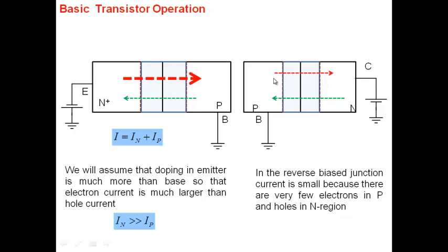It's easy. In fact, it's not difficult for an electron to go from P to the N region. If you look at the direction of the electric field, it helps the flow of electrons. So that's not the reason why current is small. The reason is I have very few electrons here. So understand, the bottleneck to current flow is not that it's difficult to move from here to here, it is that I have very few electrons here. And by going from 1 volt to 2 volt to 3 volt or 4 volt, I don't do anything to the supply of electrons here.